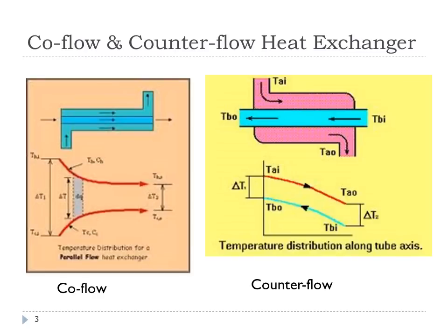So there's two main types of heat exchangers as far as which direction flow goes. You can also have a third type, which will be even more complicated, where the flows are perpendicular. But here we're going to just take two simple cases. One is co-flow, in which the flow is actually going in the same direction.